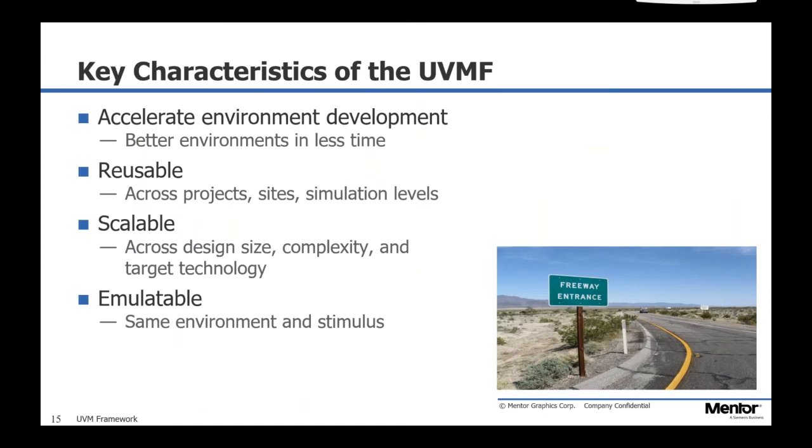So the whole point of the UVM is to accelerate your test bench development, to get you running a UVM test bench way faster than you could ever do it by yourself. We've thought about the pitfalls and all the things that say, I want to pick this agent that I created for this project up, and I want to use it not just at the block level for this thing, but I want to use it at the system level. I also want to pick it up and I want to use it in a different project. So we've thought about the pitfalls of the reusability and the scalability and everything.